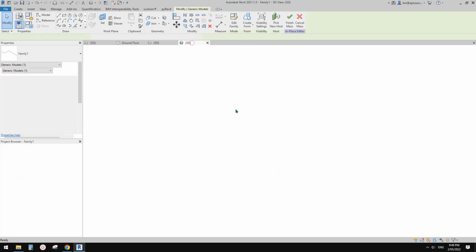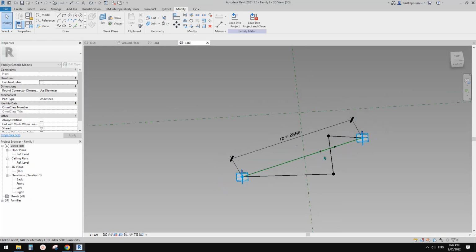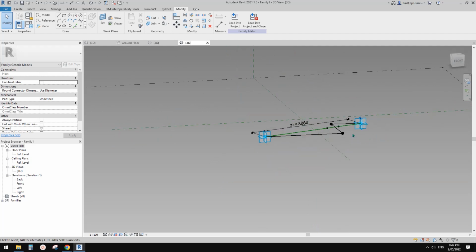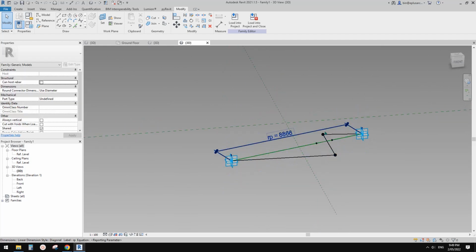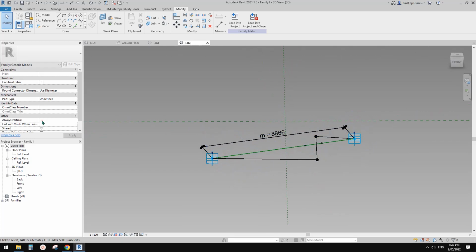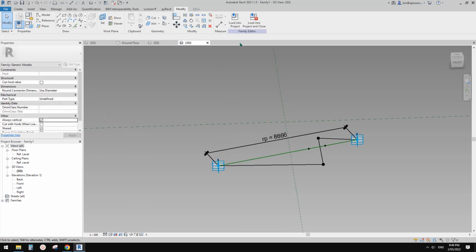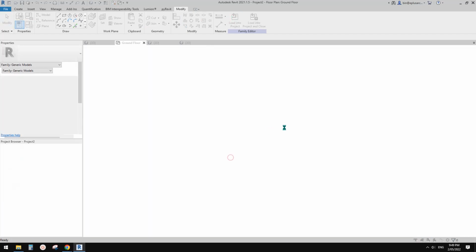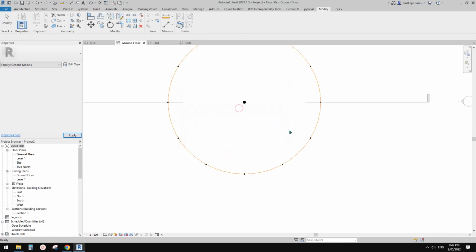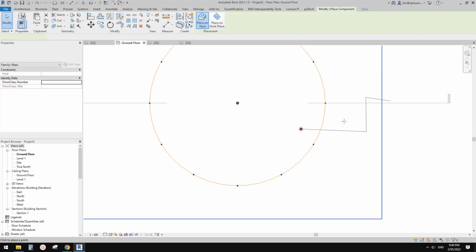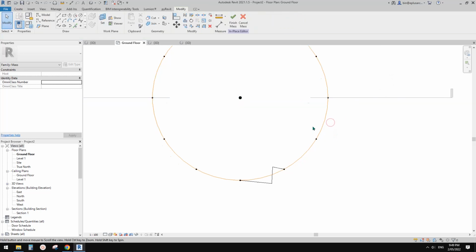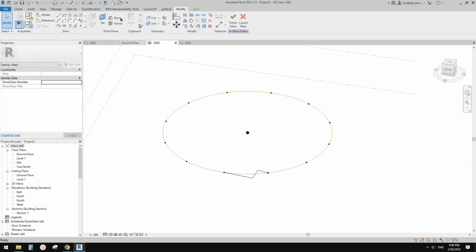So we just need to go back because when we draw this adaptive family, it's supposed to be horizontal. So if we wanted to keep the orientation, so just check this one, always vertical. Load this back. Okay, overwrite. So now it disappeared. Don't worry. Just place another one somewhere. Delete. All good. Go to 3D view.